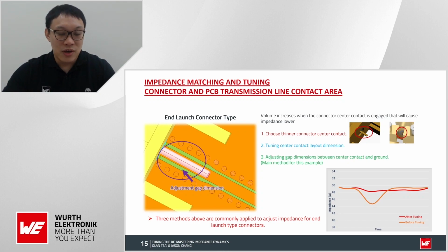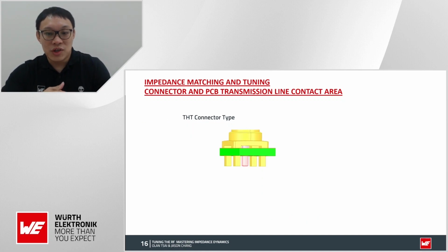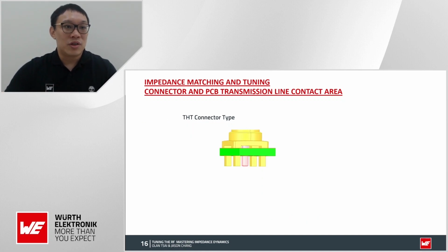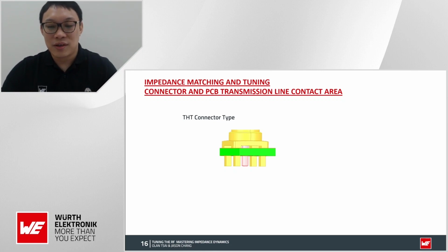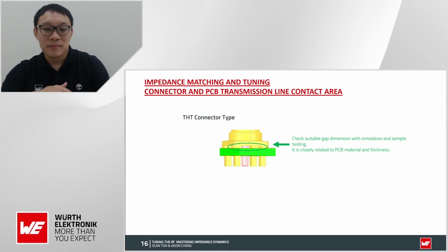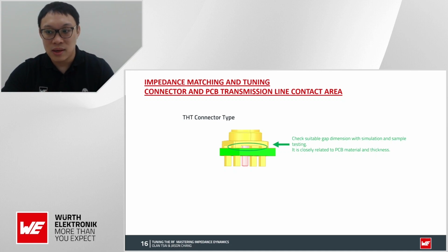Okay, this is for N-notch. Let's move to the THD connectors. The THD connectors are a little bit difficult, I think. First, you can check the gap dimension between the connector body and the PCB. And with the simulation software and actual sample testing, you can know which kind of height or dimension would be more ideal for you.